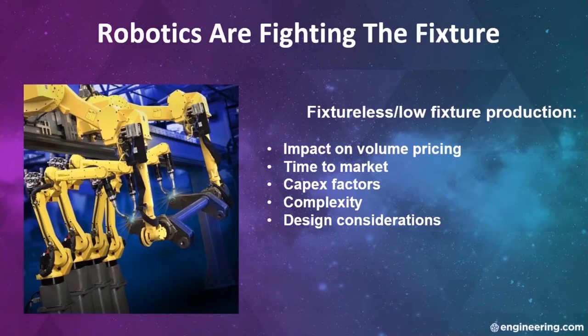Now, from an assembly design consideration, applications like this have one major advantage, and that is they act as dynamic positioning systems rather than static fixtures. The ability to invert and rotate the part during work can allow the engineer to design assemblies of formerly difficult to reach attributes, and especially fasteners, splined and threaded parts and subassemblies. It's simply easier to get things to go together if we can rotate them and invert them in three-dimensional space.